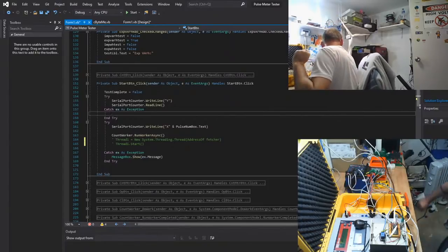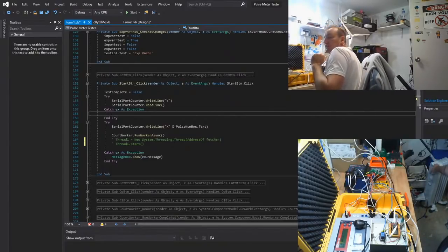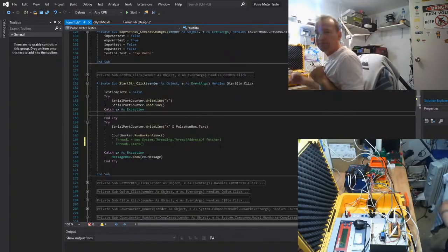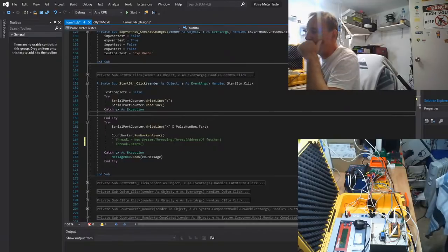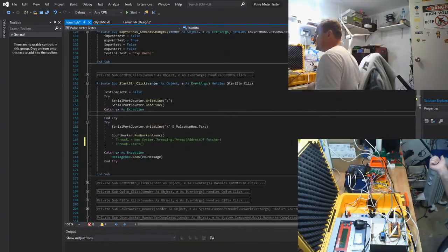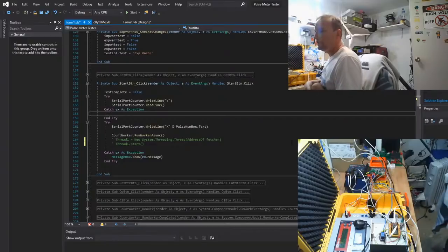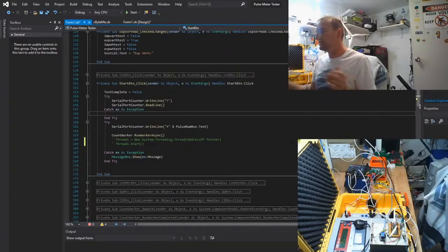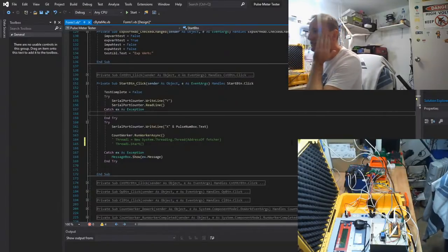Yeah, so that is the heater. That's a load I'm using to measure. It's like phantom load, they call it, or a phantom load sort of system. To calibrate meters and stuff, you can either use a generated current and voltage or a phantom load system. In this case, I've got a phantom load because the thing that I've got to create current and volts is too loud. I can't be bothered listening to it.